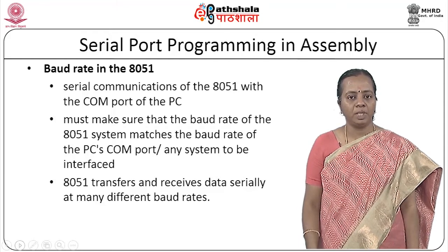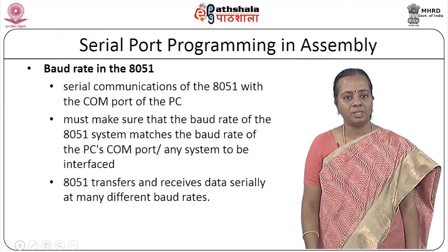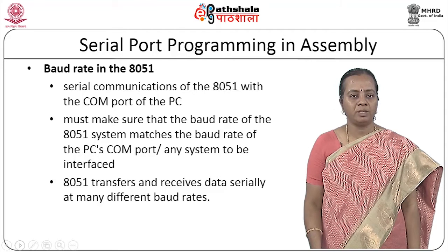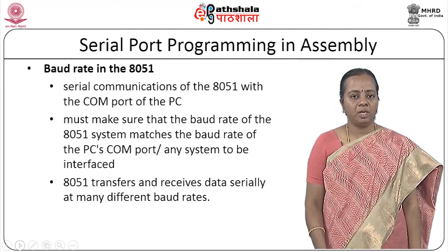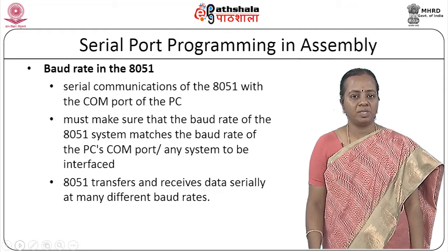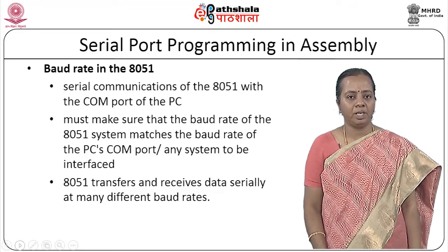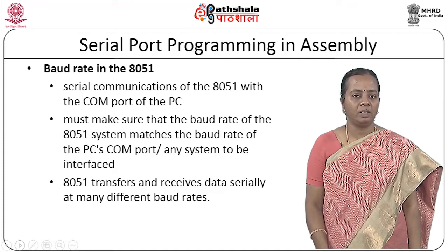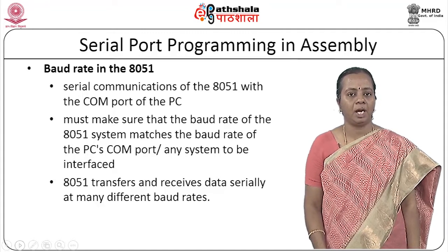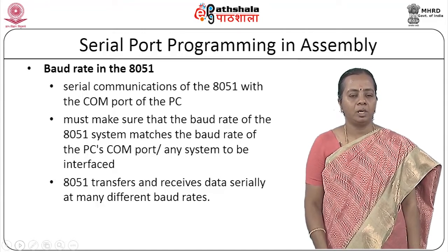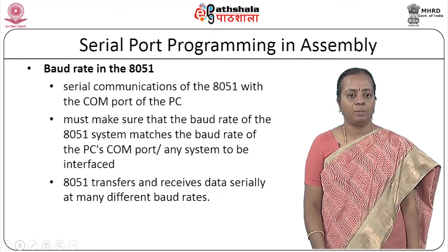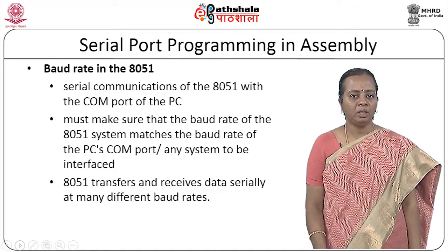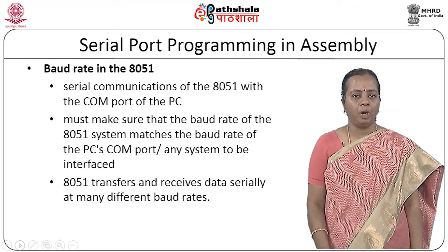If I am reading something from an input device and the input device gives data to the 8051 in serial mode, then we need to know the speed at which it will be sending the data. The 8051 is then configured with that speed to receive the data. That speed, in bits per second, is what we call the baud rate.